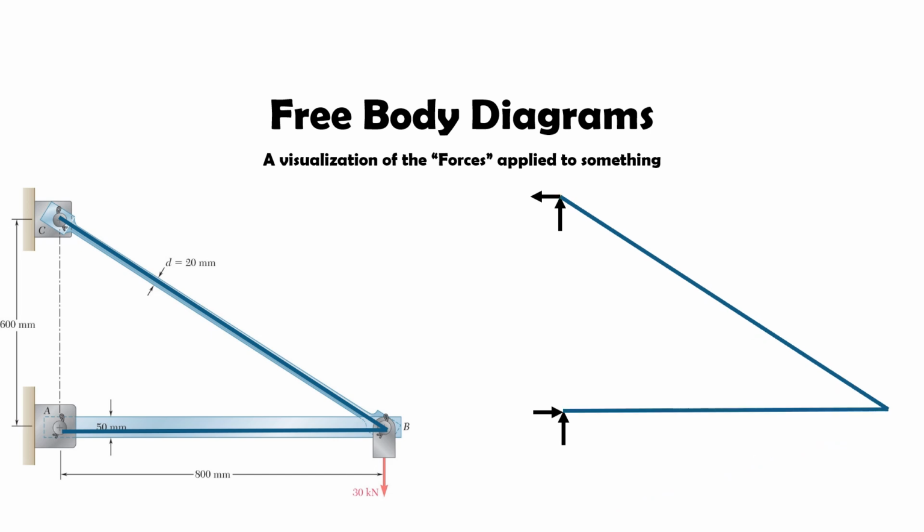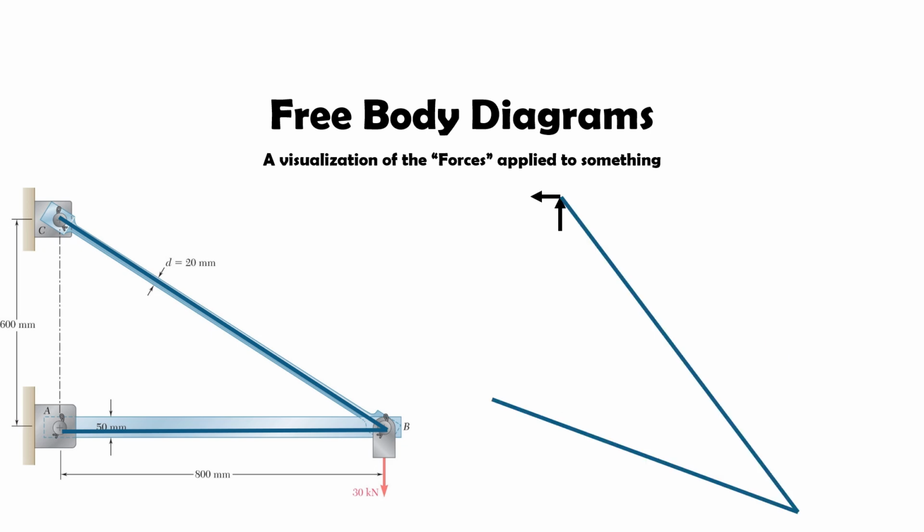Let's go back to the initial system. What if we remove that pin outright? So we remove both the horizontal and vertical reactions. Well, in that case, the whole system rotates or falls. This means that all of these reaction forces are needed to represent the truss and ensure it remains in equilibrium or stationary, and that it behaves as we would expect it to.